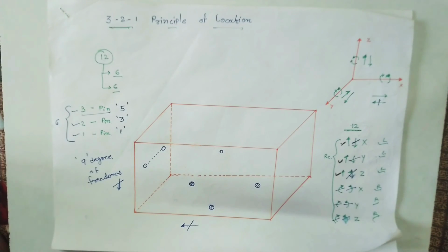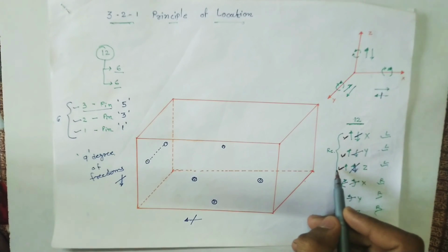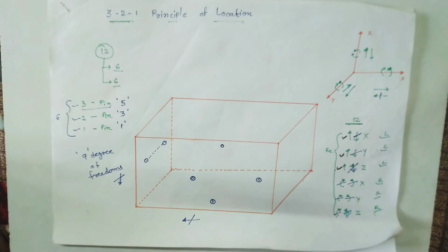For a clamping force, we can use a clamping device, a clamping screw, hook, bolt clamp, lever clamp, bridge clamp, etc. We can restrict these 3 degrees of freedom and perfectly fix and perfectly locate our workpiece